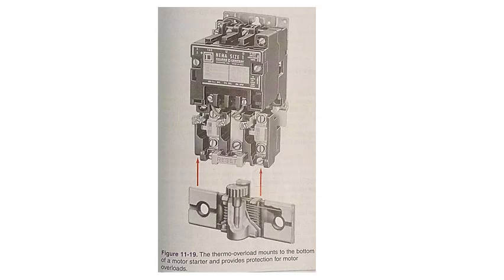A thermal overload device is a simple ratchet wheel device held in place by a metal alloy such as solder. When the overload condition generates sufficient current flow to melt the solder, the wheel is free to rotate, causing the circuit to open. This allows the motor to safely shut down before any damage occurs to the equipment or personnel. For this, see figure 11-19.